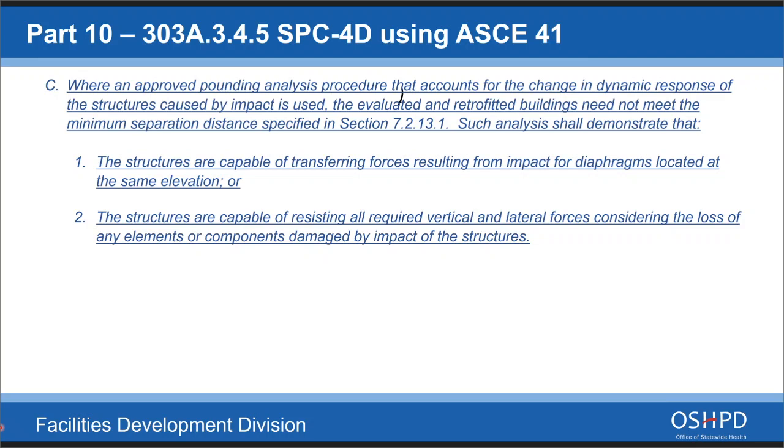But now, for those conditions, I would recommend that you actually do a building separation if it's possible, otherwise the pounding analysis. And if you do a pounding analysis, then you will have to show that the buildings are capable of transferring those forces without collapse, or you don't, for each of these criteria. So with that, next slide, I'm done.